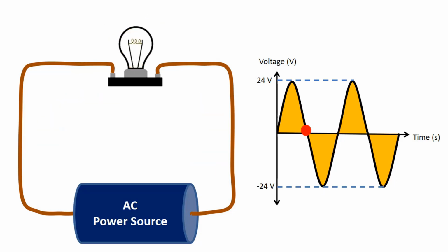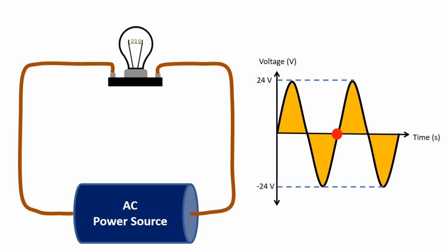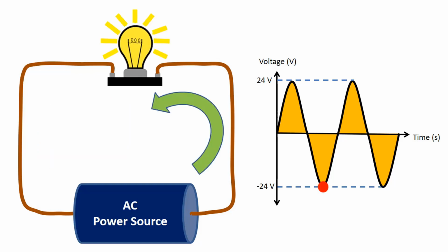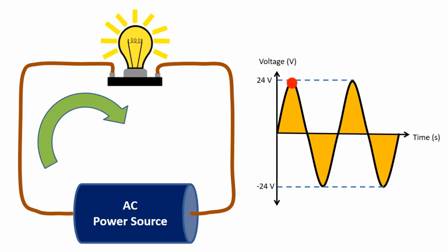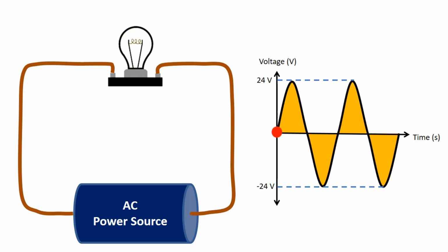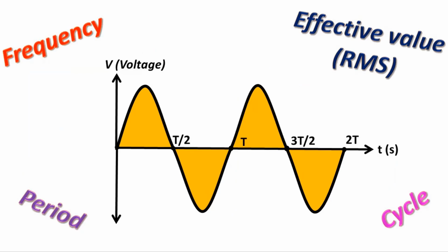We might have a question like this. We use AC, so do the incandescent lamps we use flash in this way? Yes, that's exactly how it happens, but we can't notice it with our eyes because the flashes are so fast. In the USA, the frequency value of the voltage we use at home is 60 Hz. This means that our lamp blinks 120 times per second. However, our eyes cannot detect more than 20 flashes per second. For European countries, the frequency is 50 Hz.